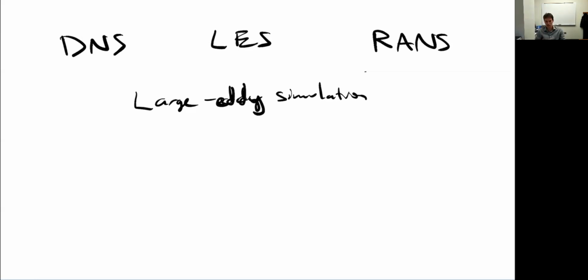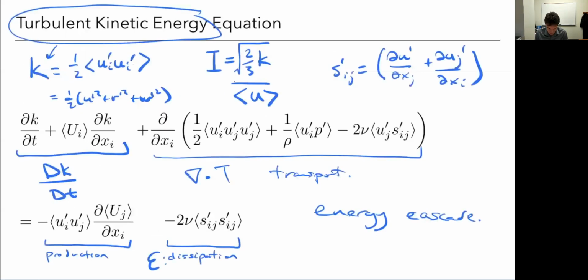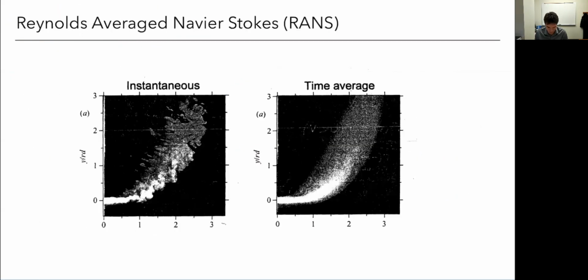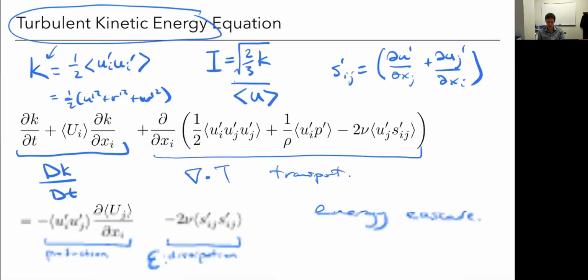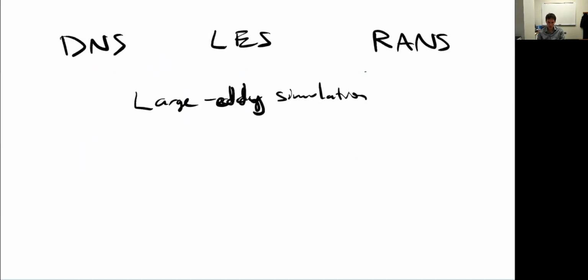If I go back to this picture here, it would be like I've got this flow thing here. Each instant in time it's averaged, and I could move it around, right? That thing could change, but I'm still averaging the flow field at each instant in time. So just to make that clear, I can have unsteady RANS, also called URANS.